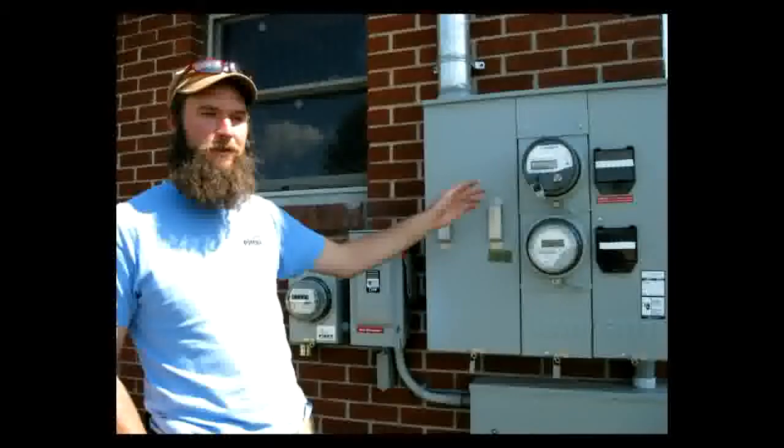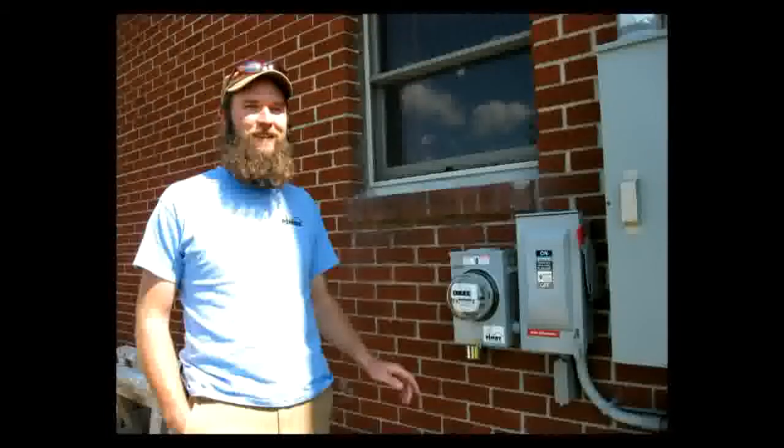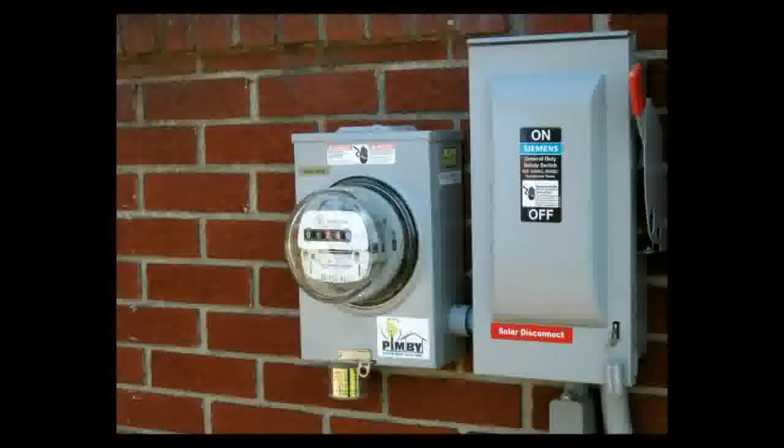If you look at the electric meter here, this is an old mechanical meter that I've installed, and it shows you by spinning here rapidly that we're making a lot of power from the sun. There's a couple of things that are common to buildings that are net metering customers or grid-tied customers, and they include a disconnect with a handle. This is required by net metering law in most states.